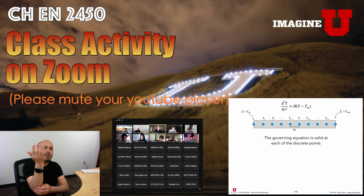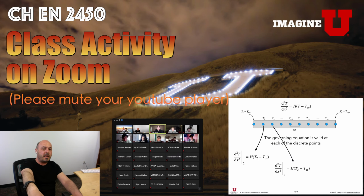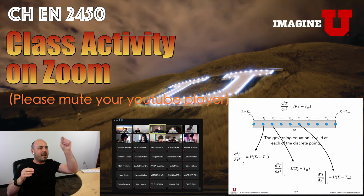All right. So therefore, at point 2, the equation is d2T by dx squared at point 2. Notice the indexing that I'm using. The second derivative at point 2 is equal to h(T2 minus T infinity). Okay, pay attention to that. We're applying now the full governing equation at each of those points. And same thing, the second derivative at point 3 is equal to h(T3 minus T infinity). Okay, that should make sense to you. It's like applying an algebraic formula, e to the x. You apply it at any value of x. The same thing we're doing here, okay?